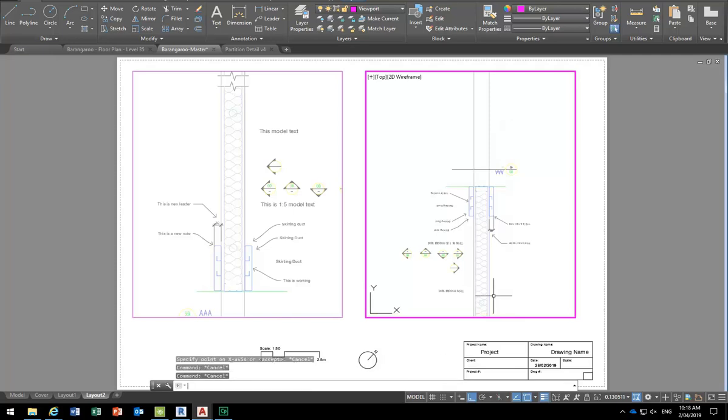Yeah, because it was already rotated 90. So I'll start on the original. Okay, so UCS, 90, Z, enter, 90, enter. So now it will be another 90 because there's the X perpendicular to our viewport.